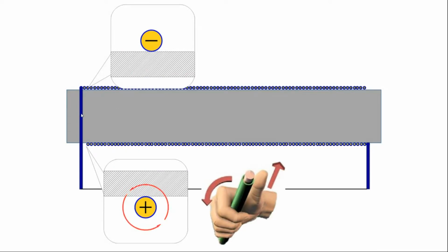And then on the top here, this is showing one of these wires, and I have current going into that wire. That's why I'm showing a minus sign there, because current returns to the negative terminal of a battery. And if you point your thumb into the screen, you'll notice your fingers will be rotated in a clockwise direction. So that is why I show an animation here of the rotating field in a clockwise fashion.